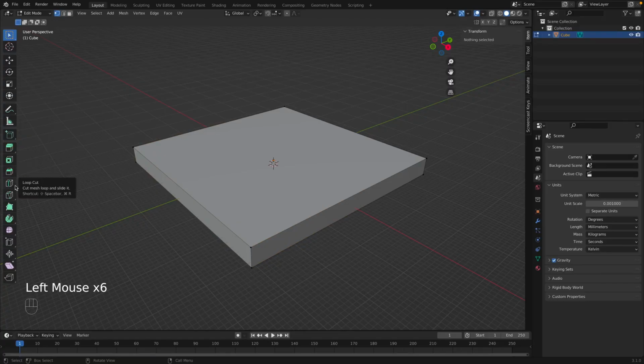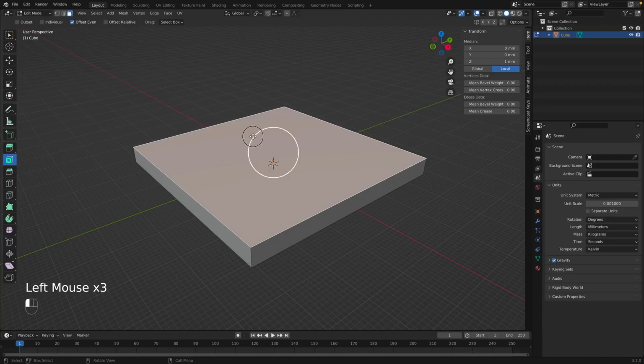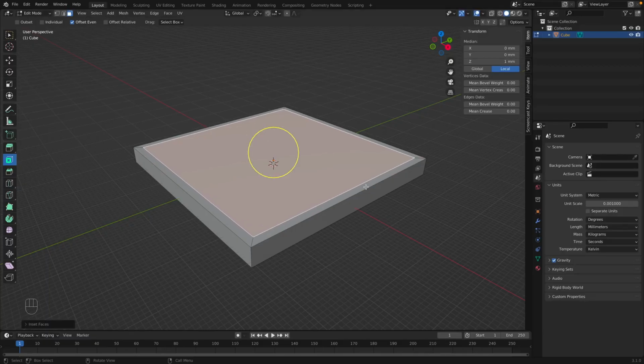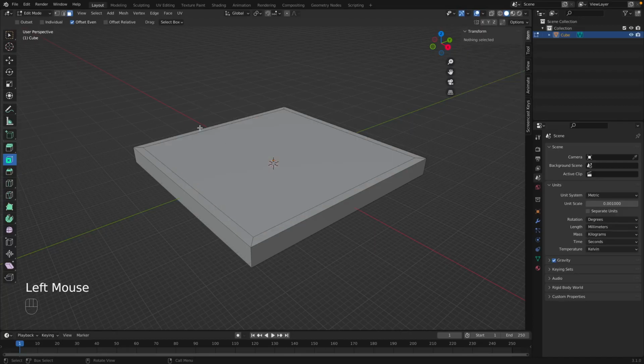On the left here are a bunch of tools that we can use. There's extrude, there is inset, bevel, and these are very common tools that you'll use. For example, let's do the Inset Faces tool. So we select on Inset Faces, and we'll actually have to, it looks like we'll go back into the face selection mode, and we can select on this face. And now if we grab this here, you can see we're insetting that face. So basically, it's allowing us to create some walls here. Okay, so once you have the thickness of the walls that you like, go ahead and click.